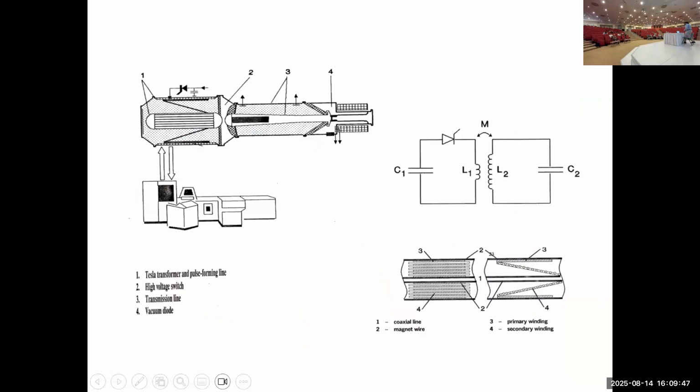So this is our sinus machine. This is a very nice cartoon. Basically, you have here the primary capacitor C1, and this is the thyristor. And then the primary winding is 1 turn, and I think Artem described this in more detail first Monday. And this is the 3,500 step up transformer. Once you fire your thyristor, the signal will come from the primary to the secondary, and then comes to this spark gap switch. This is a spark gap switch under pressure, a nitrogen pressurized switch.